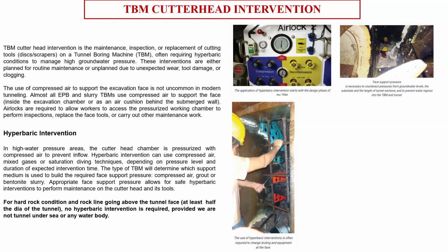Initially we tried to raise or lift the segments by pushing with a jack. But then we found that we were not able to, because behind them, all the other segments were getting cracked or distorted. So what we did was some grouting to push the segment.